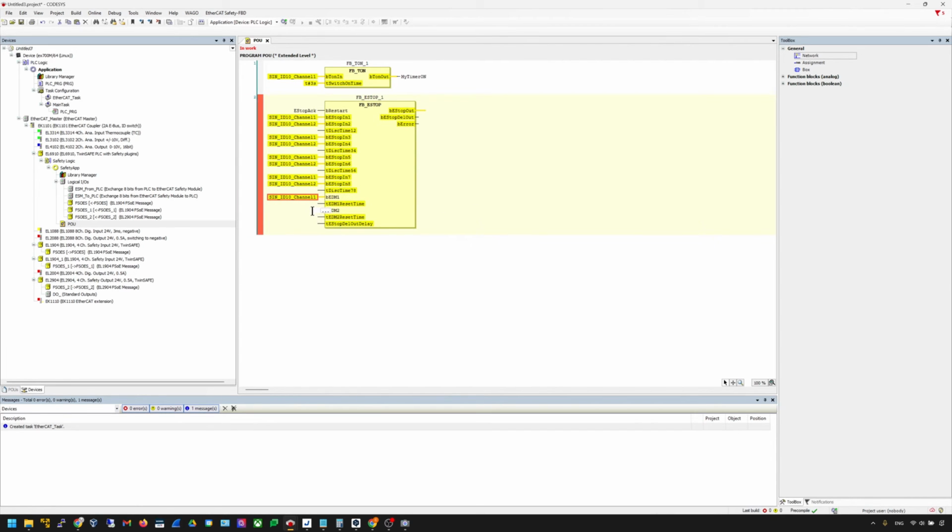Great. Okay. So actually in here, some parameters have a yellow highlight. It means they are safety variables. You need to pass the safety variables inside. So for this one, it's a normal variable. And then there is some span time. So I will just put 100 milliseconds, because at least you need 100 milliseconds. And then for the reset time, I don't need any delay in here, I don't use this feedback, so I just put 0 milliseconds.